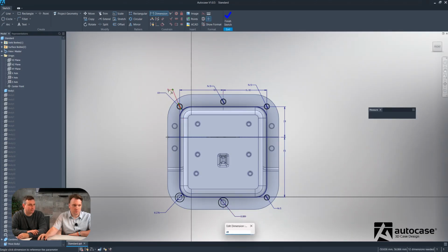And you're essentially just, instead of setting these as a dimension, we're setting these as referencing another set of geometry, which means if we wanted to, which we can show you in a moment, by changing the first one to 8 millimeters, all of those holes will get bigger, and then we can change that back to 5mm. Just makes it easier for more bulk adjustments within your model.